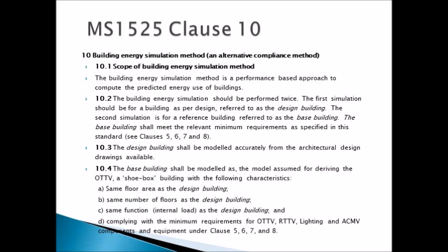The design building shall be modeled accurately from the architectural design drawings available, that is your design, but the base building shall be modeled as the model assumed for deriving the OTTV. Shoebox building, you must model it as a shoebox building with these characteristics. The base building shall have the same floor area as the design building, the same number of floors as the design building, and the same function as the design building.